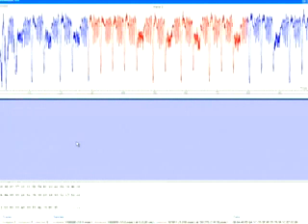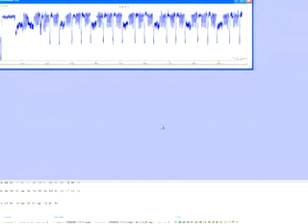And that means that it's a constant. You get square multiply, square multiply, irrespective of whether the bits of the exponent are 0, 0, 0, 1, 1, 0, or 1, 1. And because you can't see the difference between the multipliers, you don't visually see any difference anymore.